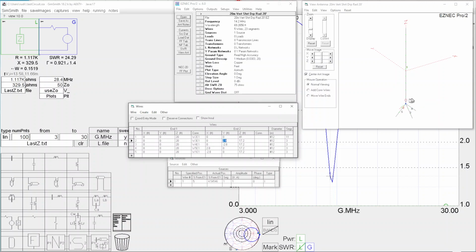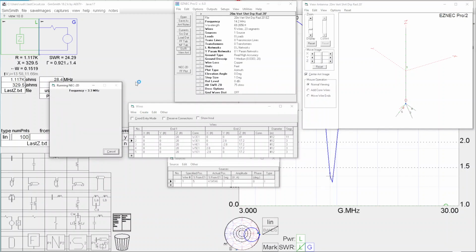But you're going to notice something. As you shorten the radials, you have to lengthen the center element, and it changes the performance because even at this feed point down here, it's a little bit like an off-center fed vertical dipole, with 4 elements on this side of the dipole and 1 element on this side of the dipole. So if you had longer than resonant radials, then guess what? It would ask you for a shorter than natural resonant length vertical whip. So just realize that trade-off. So let's run an SWR and let's see what we get.